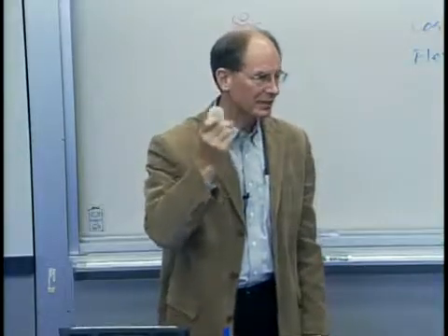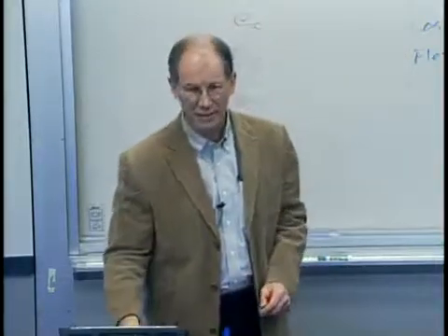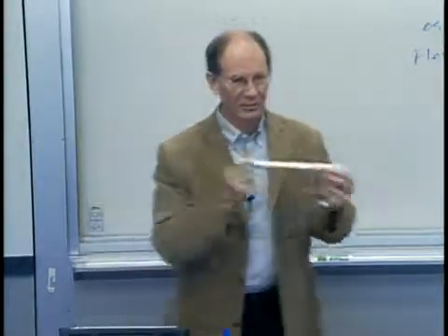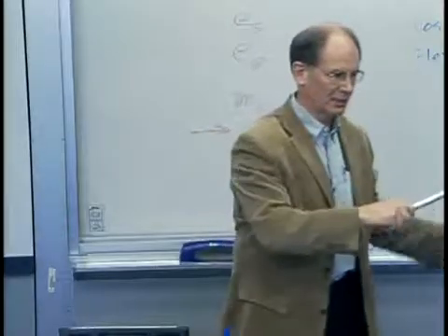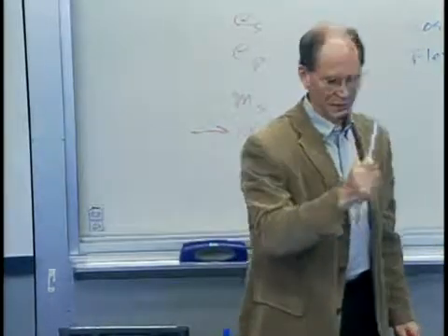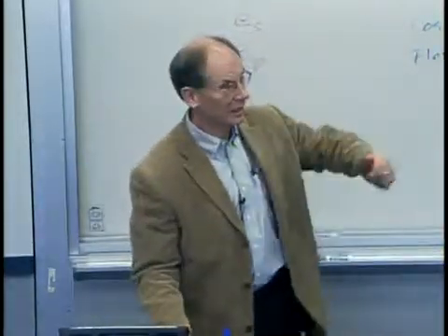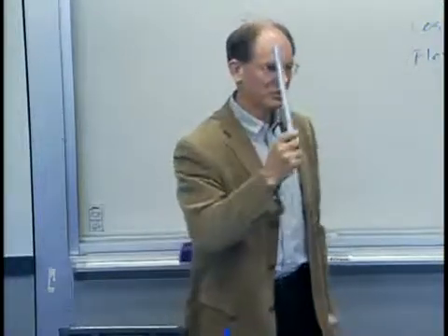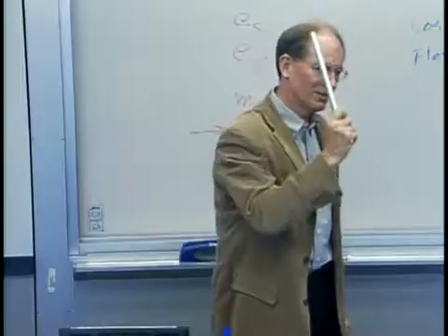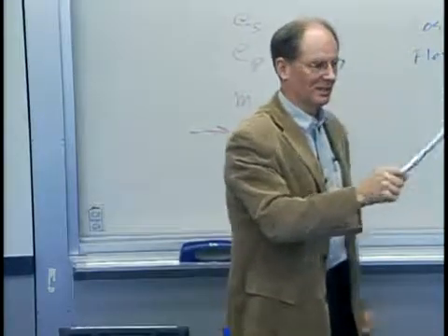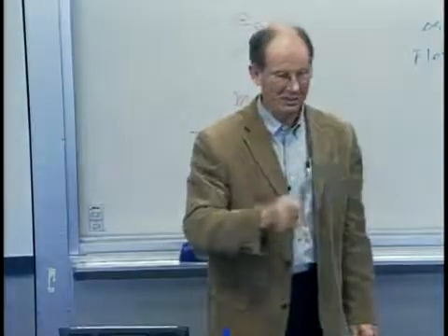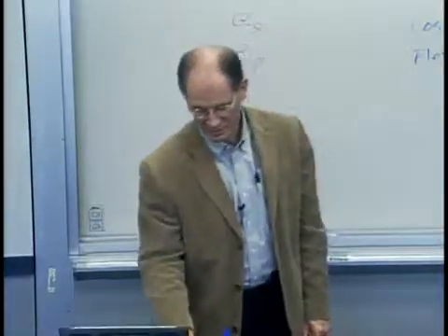Well, you know, I can do some tests and do this kind of stuff. But again, it can be shown that these can be highly variable, particularly as I go from this bar to that bar to that bar. So we're going to be able to argue that unless you spend a lot of time upstream eliminating variations, like unless you do really good process control on the casting and turning, or casting and rolling and other processes that go into this, this will have variable properties.